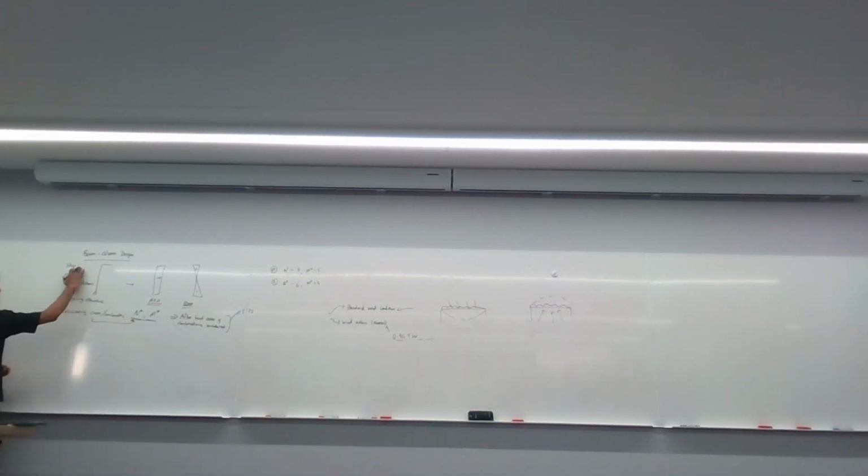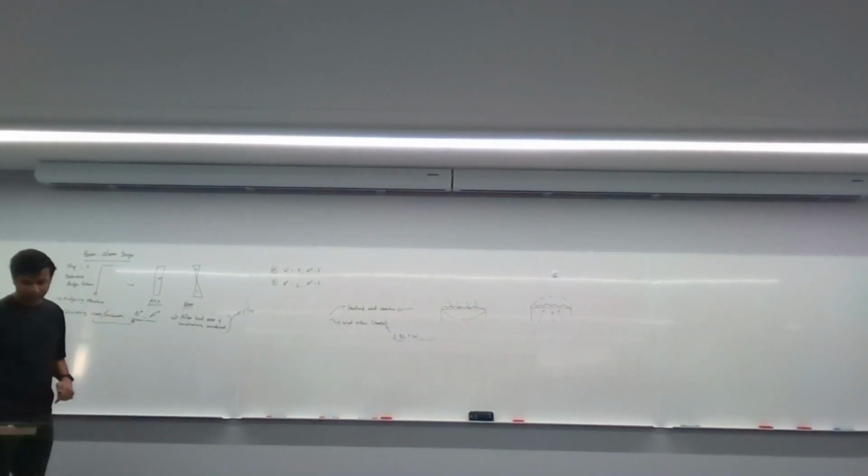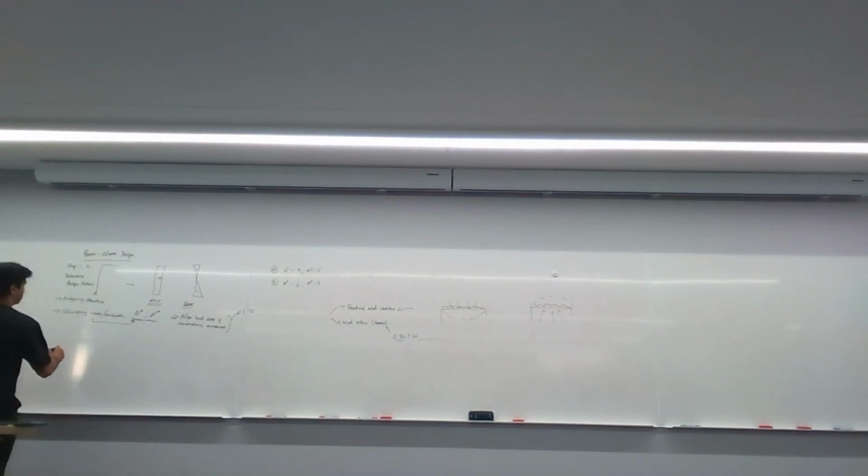So in fact, this is step 1 and 2 really. If step 1 is determining what load combinations and cases you're going to use, step 2 is analyze the structure and do your bending moment, shear, axial force diagram calculations. That's all step 1, step 2. Okay. Now, step 3